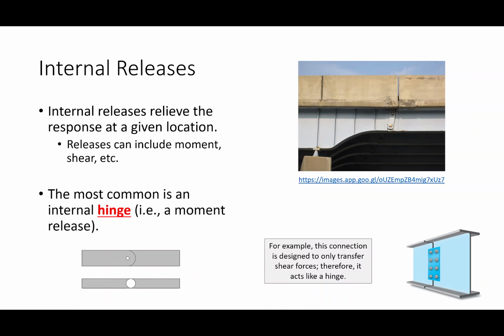If you find some older bridges that have a connection that looks something like this, it's called a pin and hanger connection. It actually acts as a hinge. Back in the day, I'm talking 30s, 40s, 50s, you've got to understand, we had slide rules. We did not have computers and calculators that could do complex structural analysis for us. And for one, regardless of computers, you don't ship a 500-foot long bridge in one 500-foot long beam. You ship it in pieces and you assemble it, right?